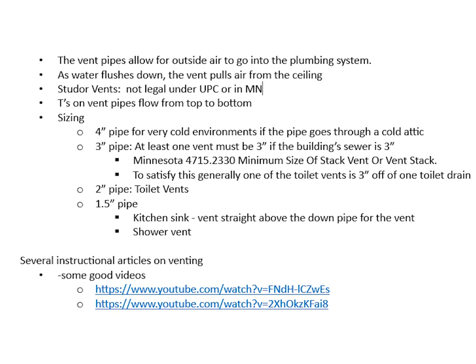2-inch vent pipe: toilet vents. 1.5-inch vent pipe: kitchen sink, vent straight above the downpipe for the vent, or the shower vent. There are several instructional articles on venting, some good videos, and the URLs are below.